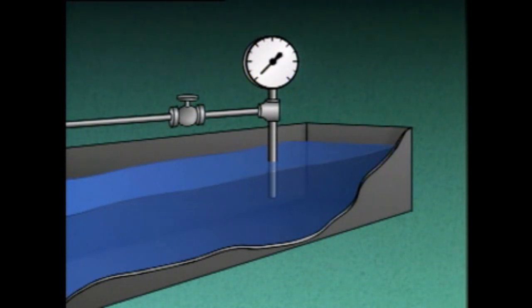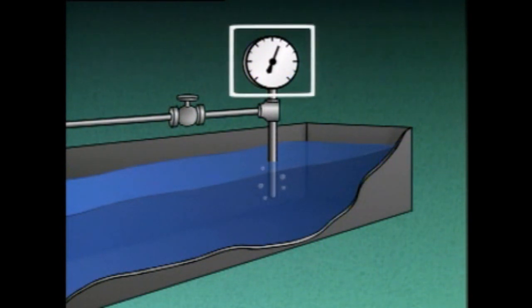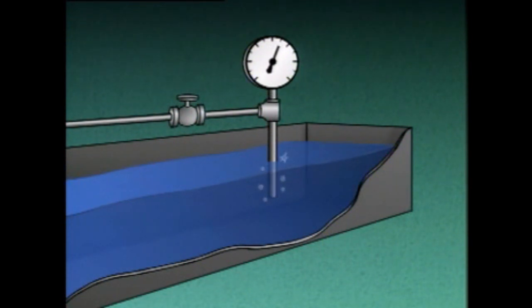The level of the liquid in the tank can be measured by adjusting the air supply until bubbles slowly come out of the bottom of the pipe. At that point, the air pressure felt by the gauge represents the amount needed to clear the pipe of liquid. The gauge uses the pressure that's exerted on it to provide an indication of the level of liquid above the opening in the pipe. Pressure gauges and bubbler systems are used in applications where the tank is not pressurized. They're not designed to measure the levels of liquids under pressure.